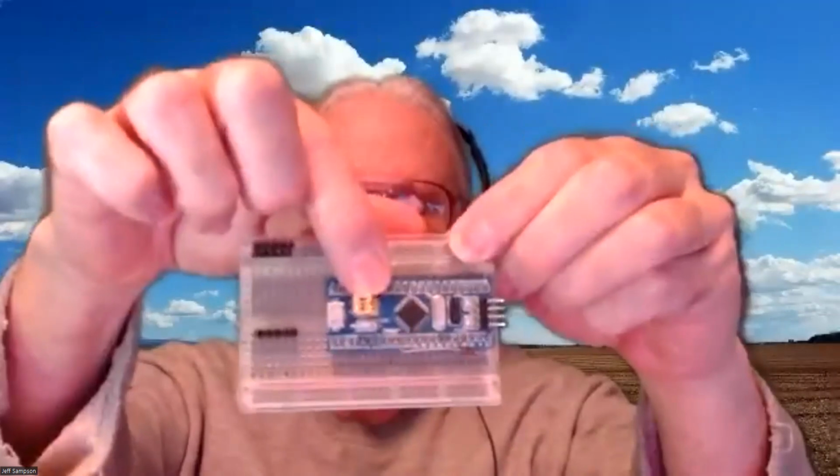Oh, the other thing I was thinking about was, how do you develop? Well, one thing you can do is get a standard plug-in proto board and just stick the board down. These are header pins with extra long pins, so you can actually plug that into the proto board. They have pins sticking up where you can just put the little jumper wires onto. In fact, the one over here has 2 rows of those, so I've got power and ground I can get to for extras, like the encoders, which I have to hook up. So you can put these in and then just run wires from here over to the board wherever you want to plug them in. So that'd be one way to develop that.